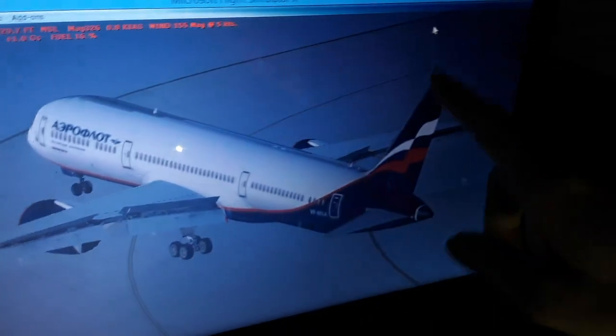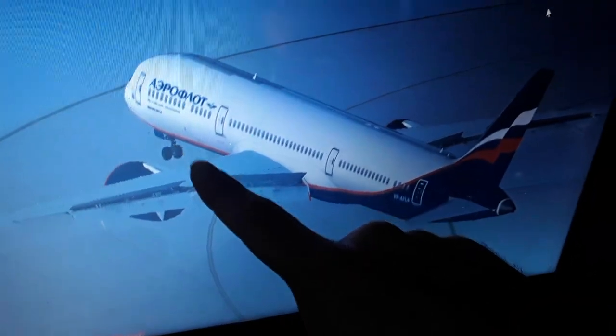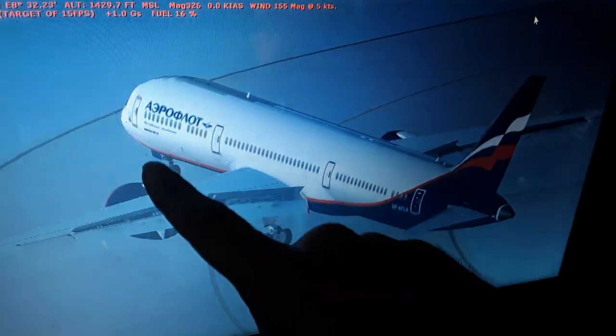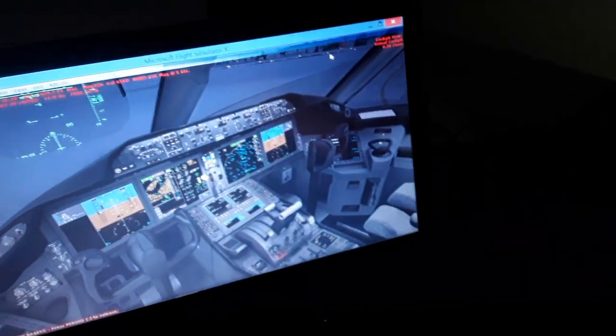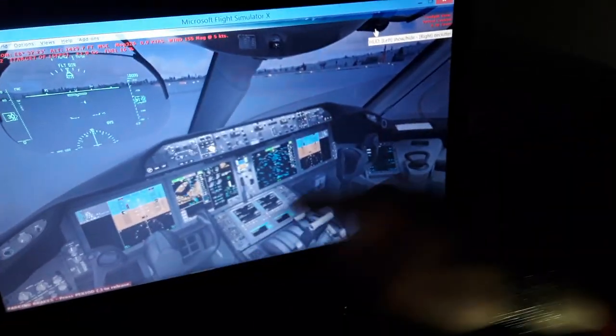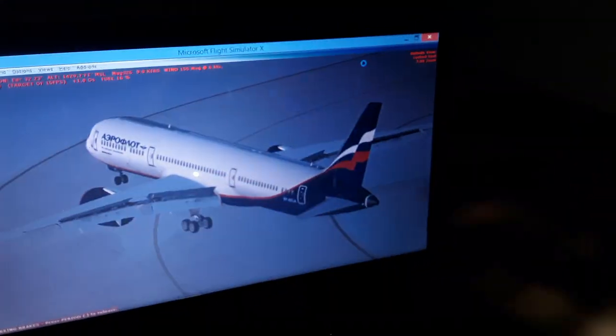After touchdown, first you have the rudder, then as you slow down the aircraft on the runway, the computers will let the forward nozzle come in for directional control. So this is the theory of the rudder pedals. We have a couple more controls over here.